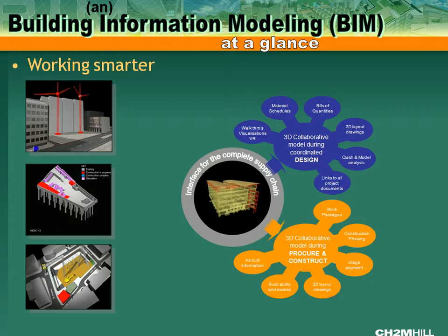Once the information is collected and received, they can start to build the as-built information. So for example, if there's a pump in the design model, the pump may be placed in the model based on 1 to 3 possible specified manufacturers. Once the pump is procured, this model can then be updated with the actual information, the as-built information for the pump, and that's inserted into the model and then passed off to operations. This same process occurs, in theory, for every single building component that exists within the model, and thus, when the model goes to operation, it's rich with as-built information.